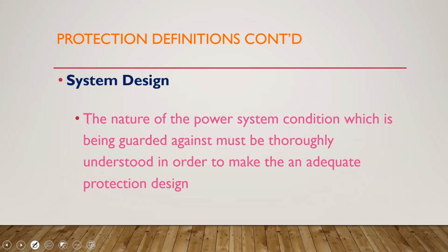Okay. In machines 2, you're going to look at your star delta transformer. In terms of the operation of that transformer, you have to think about the phase shift that's going to occur, that 30-degree phase shift. And as such, how you utilize, let's say, your differential protection is going to be dependent on you understanding that theory.